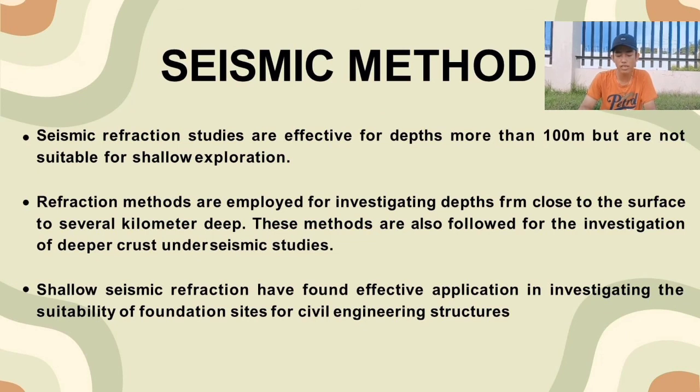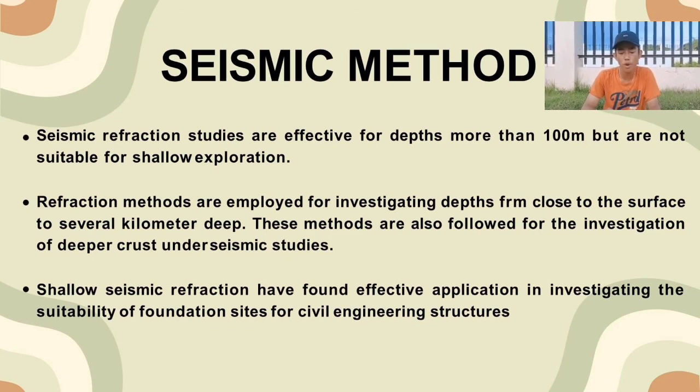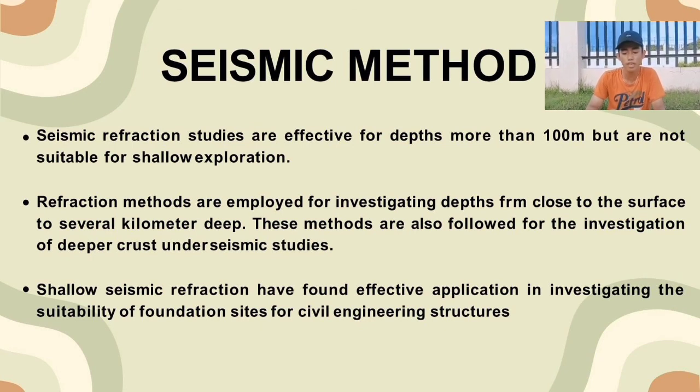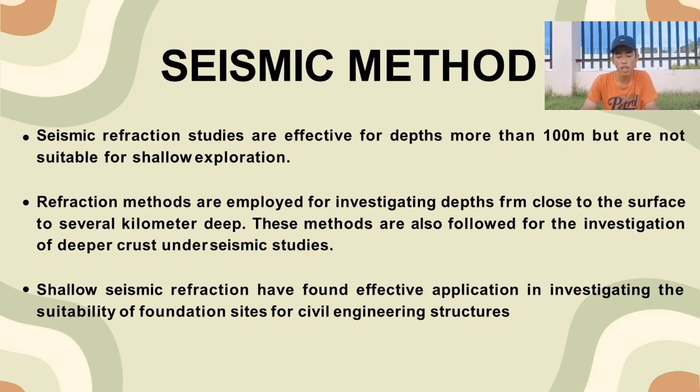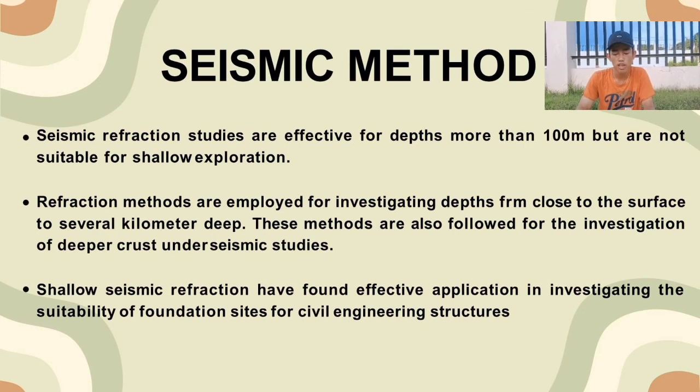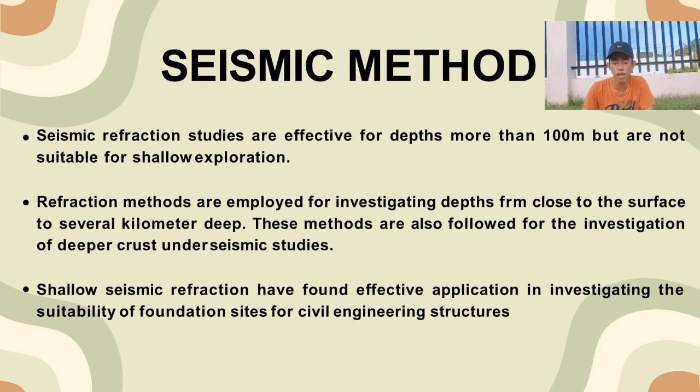Seismic refraction studies are effective for depths of more than 100 meters but are also suitable for shallow exploration. Refraction methods are employed for investigations from close to the surface to several kilometers deep. These methods are followed for the investigation of the deeper crust under seismic studies. Shallow seismic refraction has found effective application in investigating the suitability of foundation sites for civil engineering structures.